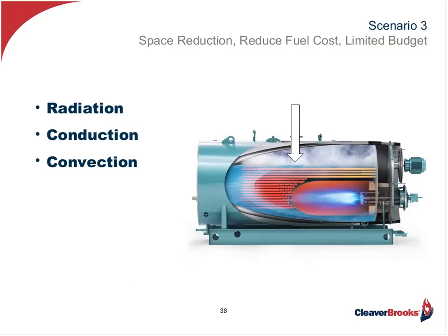And then, once that chemistry has occurred, I've got my complete combustion, I now transfer the heat through radiation, conduction, and convection. And in these modern fire tube boilers today, as they are now evolving, the smaller ones, the lighter ones, and the more efficient ones, about 50 to 60% of the heat energy is absorbed in the furnace. That's very important, because that is the most effective heat transfer surface that we have.